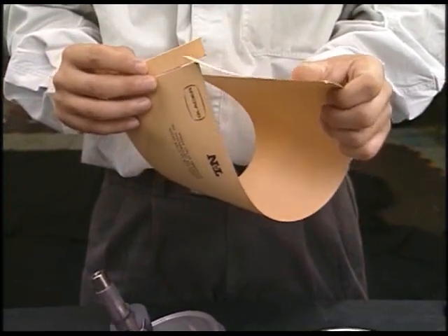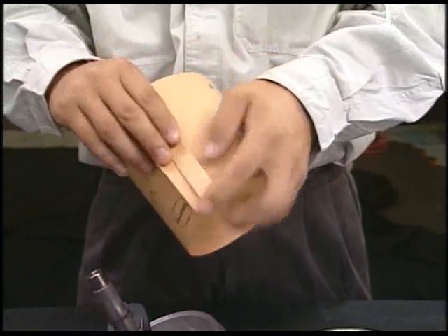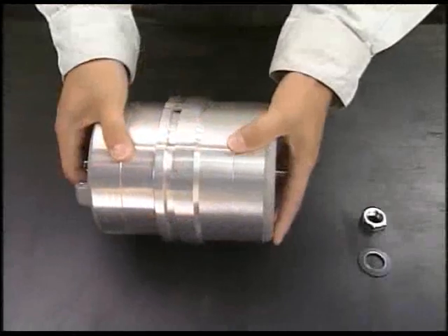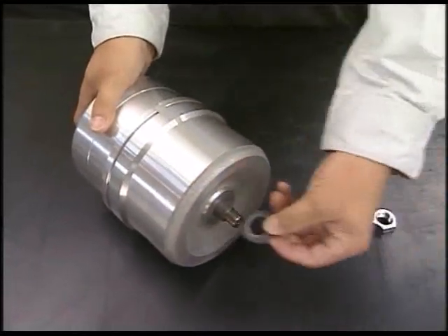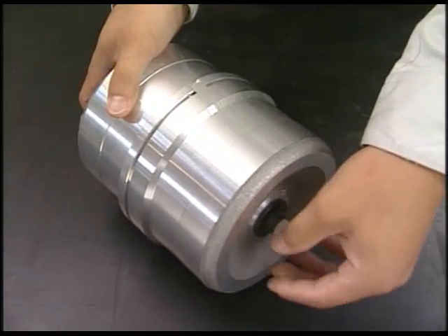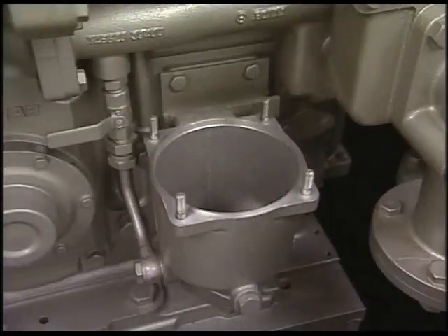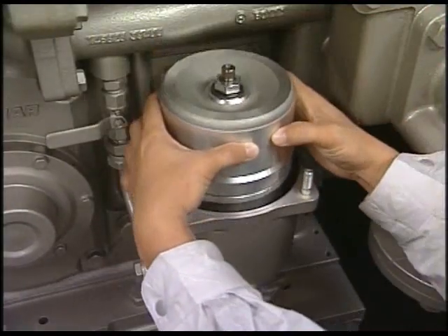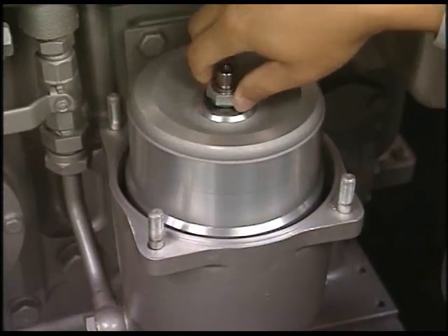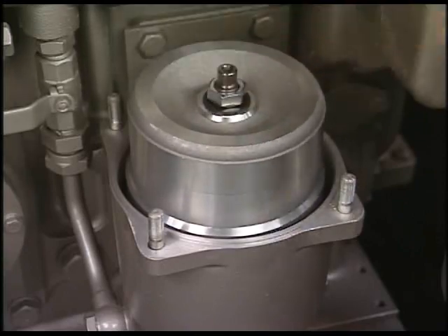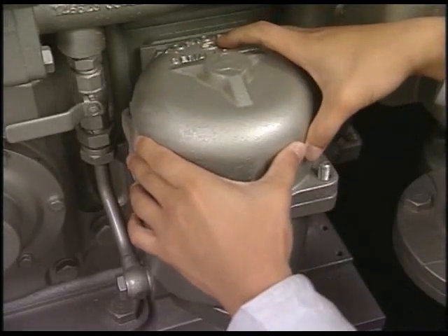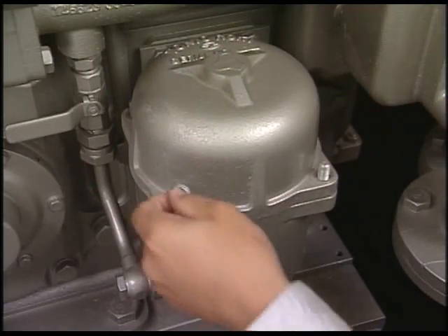After renewing O-ring, reassemble the centrifugal bypass strainer in reverse procedure for disassembly. If the paper insert is put in, it will be easy to remove the sludge next time. Fix the reassembled rotor assembly on the main body and check that it smoothly rotates. Fix the main body cover, tighten the nut, and the work will be completed.